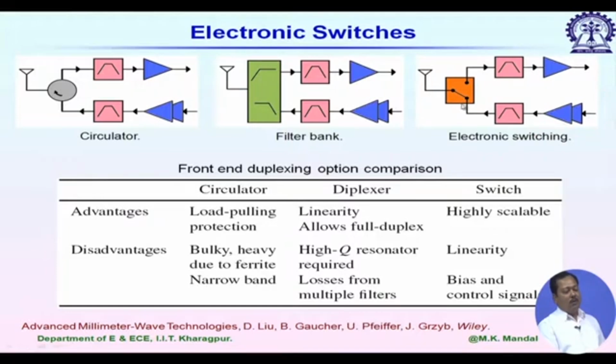So, two important characteristics it should have: very good isolation between the input side and output side, or receiver side and transmitter side, because transmitting power is very high, it can be of the order of a few watts, and the received power is typically of the order of nanowatts or even less than that.